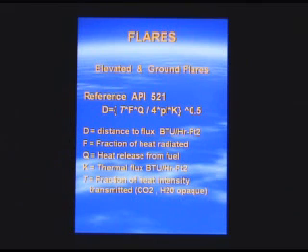So if you're in a hot environment like Saudi Arabia, which has a solar radiant flux of about 300, that says you would only be able to have an additional 200 BTU per hour per square foot from the radiant flame. So for a Saudi application, you would take 200, and that would be the value that you would put into the K here,